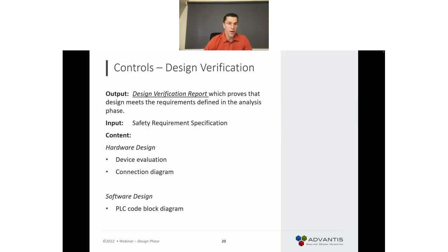So having a block diagram that separates out where different elements are in the code by providing a cross-reference to the PLC code is, in my opinion, the only way somebody can validate the code. Because only you as a software developer know where is which piece.